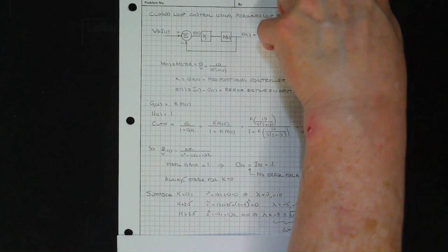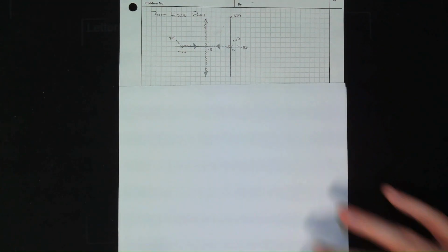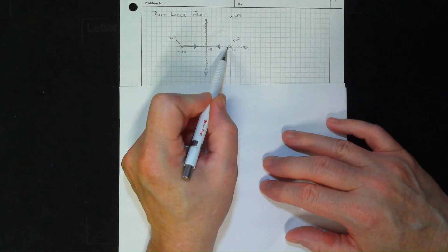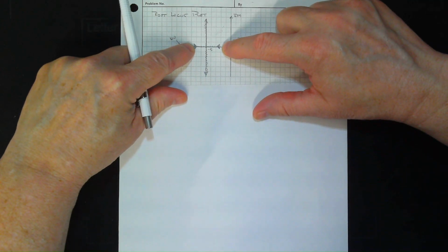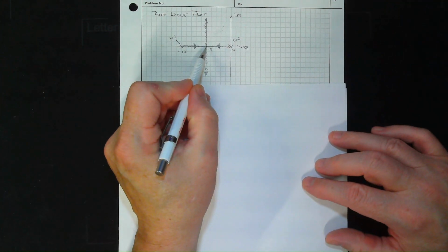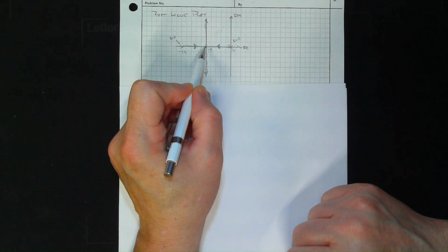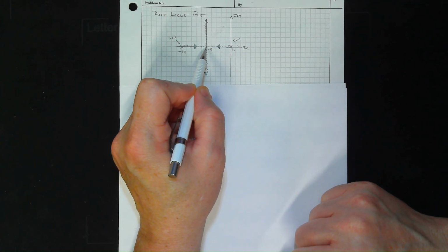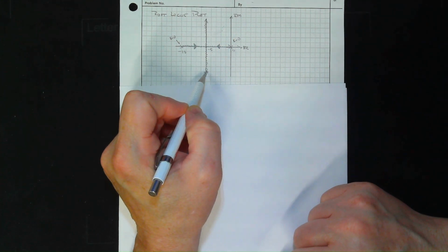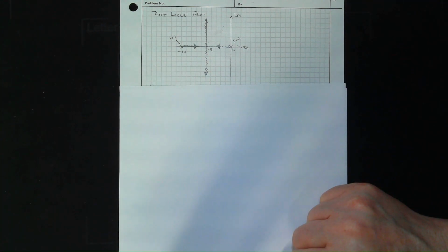Well, we can plot this. And if we do that, here, this is the plot. So when K equals 0, we start here, and as K gets bigger, the roots move in until these 2 paths come together when K equals 2.5. And then I'd have 2 roots right here, right at this point. Okay, and then as K gets bigger, 1 goes this way, and then the conjugate going the other. So we can plot the roots as a function of K.